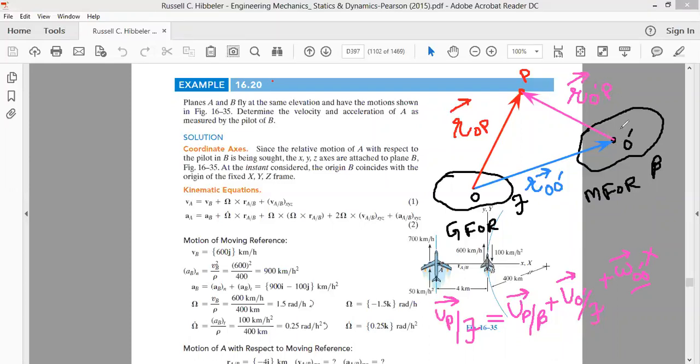As this body is having planar motion, angular velocity of the O dash vector simply means the angular velocity of the rigid body, the angular velocity of the frame of reference beta, omega beta. So in place of omega O dash, we can also write omega beta. That I will write in the next expression. The cross product is with the radius vector drawn to point P, the radius vector drawn to the rigid body from the moving frame of reference, that is R O dash P. This is the expression for the velocity. We will derive it in three-dimensional kinematics. Here we just need to use it.